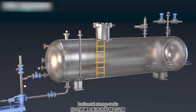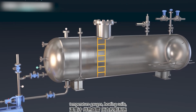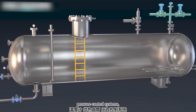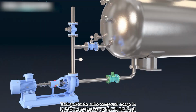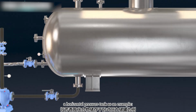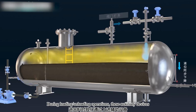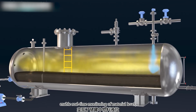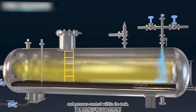Horizontal storage tanks are equipped with various auxiliary equipment including temperature gauges, heating coils, pressure control systems, safety valves, and level indicators. Taking aromatic amine compound storage in a horizontal pressure tank as an example, during loading or unloading operations, these auxiliary devices enable real-time monitoring of material level, temperature indication, and pressure control within the tank.